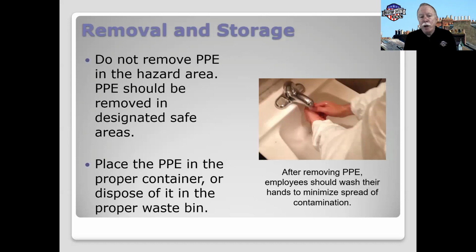You should have processes about how to clean and store your PPE. Don't just take your respirator off and throw it in your toolbox or in your bucket with all your other tools. It's going to get dirty, it's going to get contaminated, it's going to get damaged.